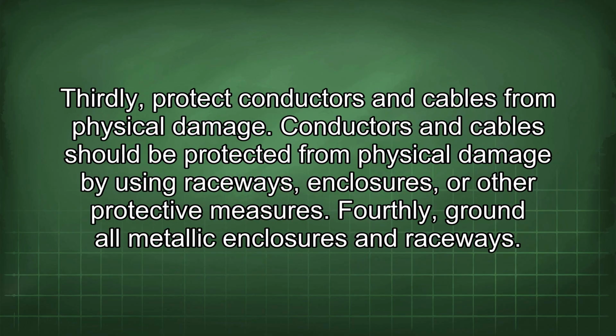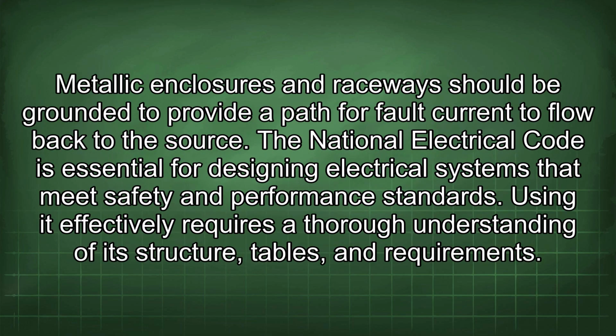Thirdly, protect conductors and cables from physical damage. Conductors and cables should be protected from physical damage by using raceways, enclosures, or other protective measures. Fourthly, ground all metallic enclosures and raceways. Metallic enclosures and raceways should be grounded to provide a path for fault current to flow back to the source.